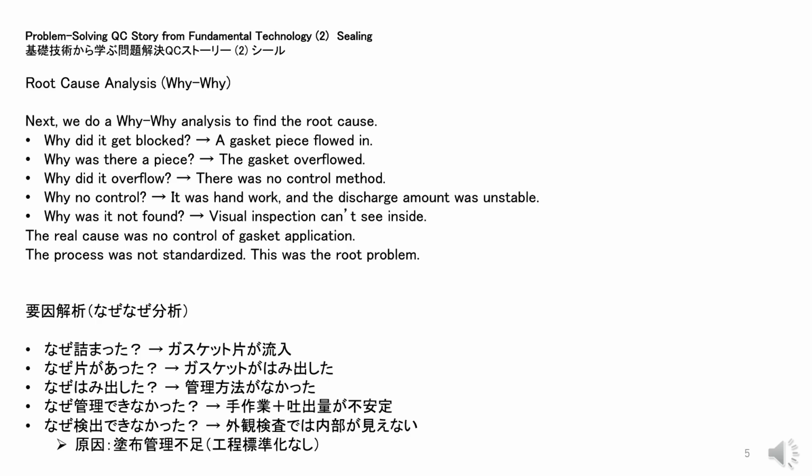Root cause analysis, Why-Why analysis. Next, we do a Why-Why analysis to find the root cause. Why did it get blocked? A gasket piece flowed in. Why was there a piece? The gasket overflowed. Why did it overflow? There was no control method. Why no control? It was hand work, and the discharge amount was unstable.